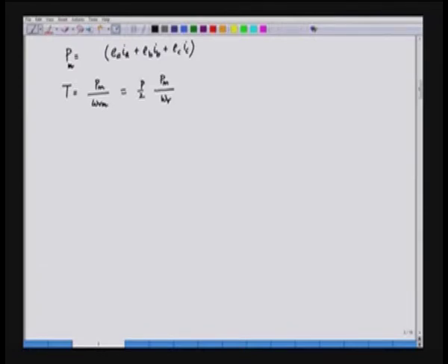So, we have P by 2 coming here, into this product we have the sum of the product of the back EMF and the currents, EA IA plus EB IB plus EC IC, and that can be written as P by 2 into this divided by omega r.